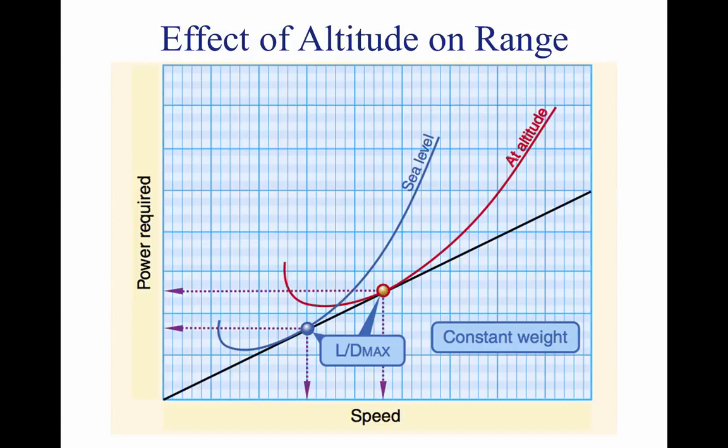The drag of the aircraft at altitude is the same as the drag at sea level, but a higher true airspeed causes a proportionately greater power required. The effect of altitude on specific range can also be appreciated from the previous relationships.